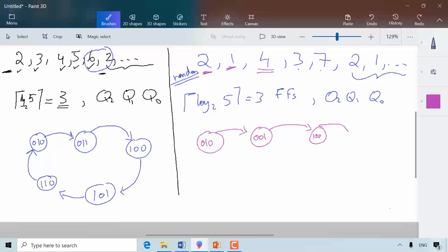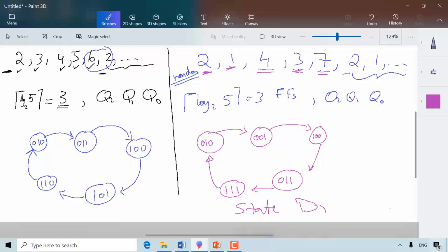Let's go back and down here a little bit, to make it easier for us. So this is 3. The next state is what? 7. The next state is 2. Go back now to the initial state of 2. So this is the state diagram, much like we have done for the previous example. And then state table, minimization of inputs, using the excitation table to get the inputs, and construct the circuit.